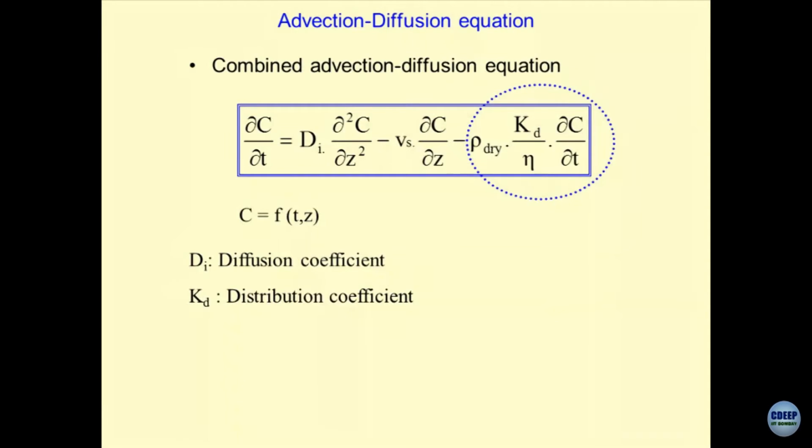Now, what is going to be difficult is how to obtain Kd parameter, because that is a new subject in itself. So, when you ask this question to yourself, how to obtain Kd, which is sorption-desorption phenomena, then we have to enter into sorption-desorption, which is a sort of chemical characterization of soil contaminant system.